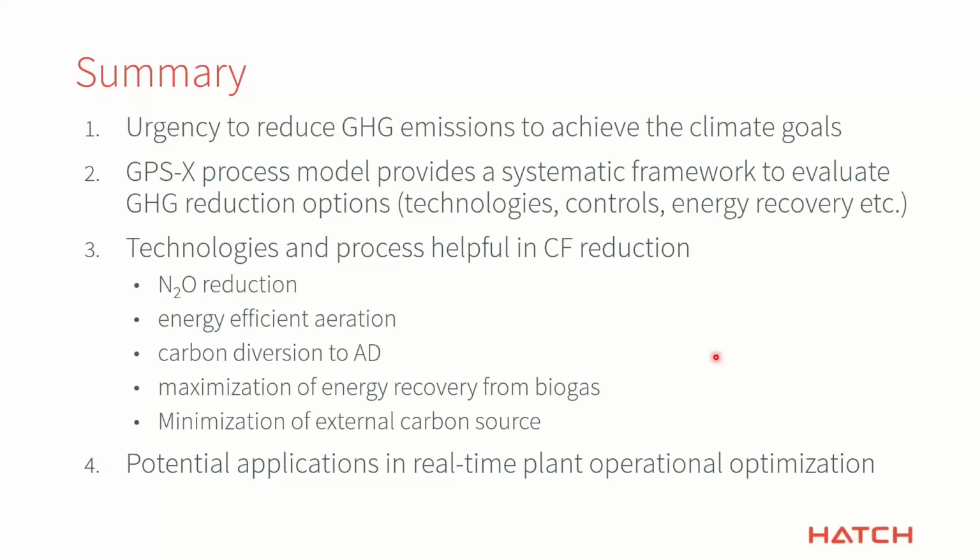The other part that I want to mention is that based on the current understanding, I do believe that the technologies that can play an important role are those having biological processes that do not add to N2O production, but can actually contribute to N2O reduction. Those could be really helpful technologies. The other one is, of course, energy efficient aeration, whether we are looking at, for example, improving our aeration grid, or our biological system, or using some innovative ways of aeration that could reduce the energy. That could go a long way.